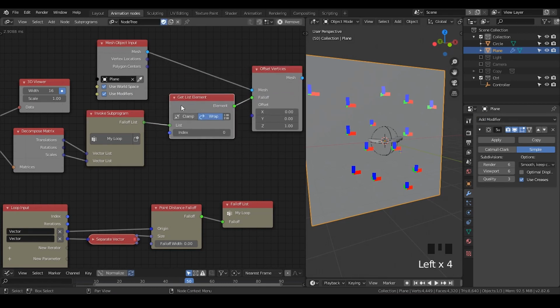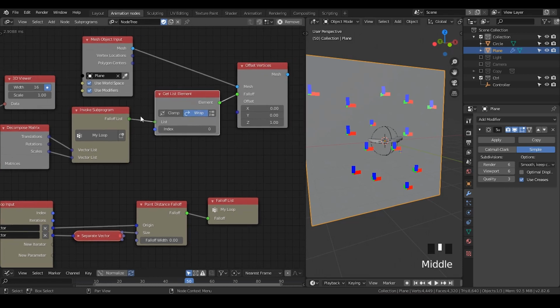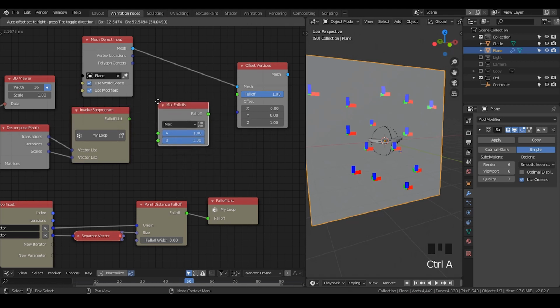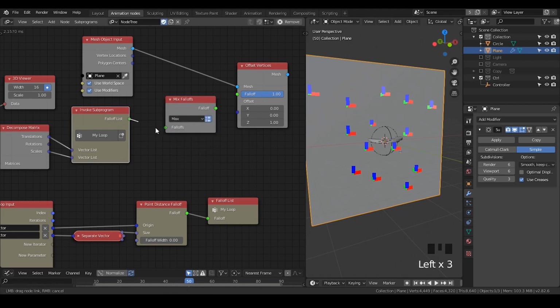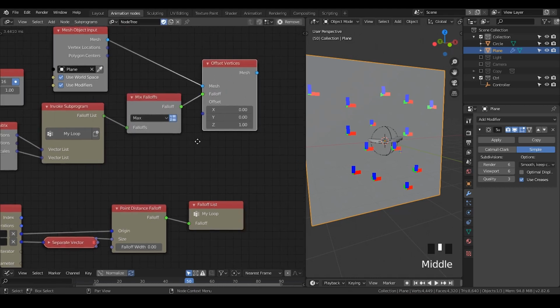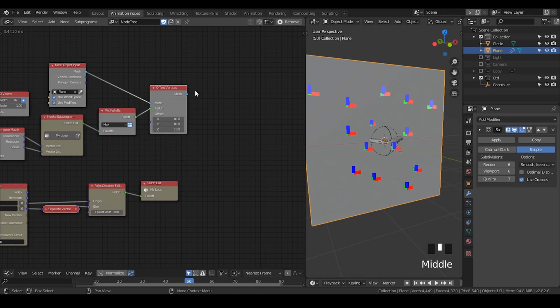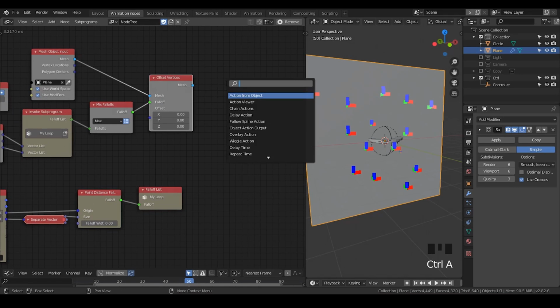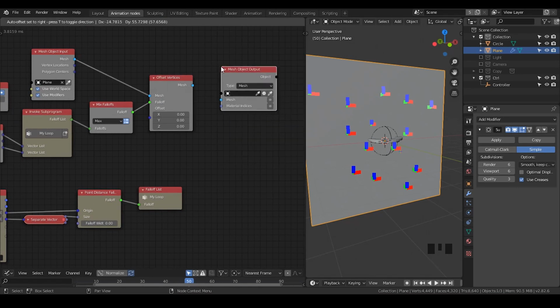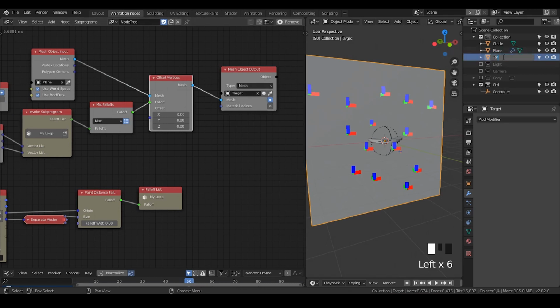And it actually does not work again, because this force has to receive a single force instead of multiple. So does it mean I need to still run a loop? No. It actually means you need to mix the force. And then let's hit this list icon. So in this case, we're merging all the forces into a single force that can be plugged in. So now we have the offset vertices, and then we need to output this new mesh. So now let's add a target plane.